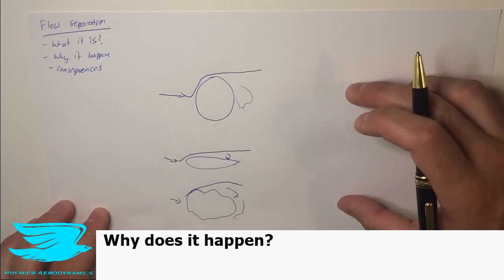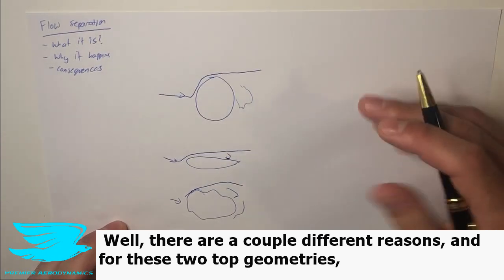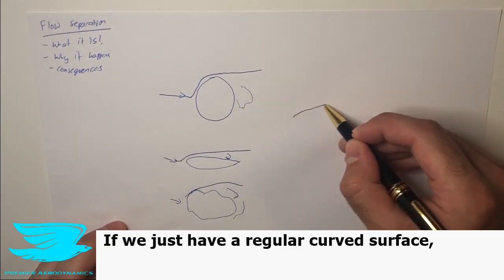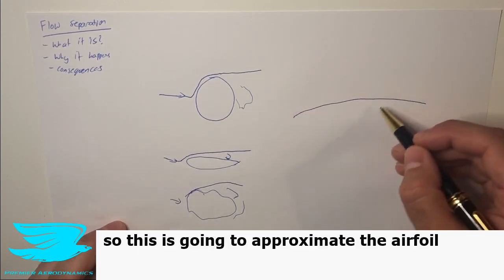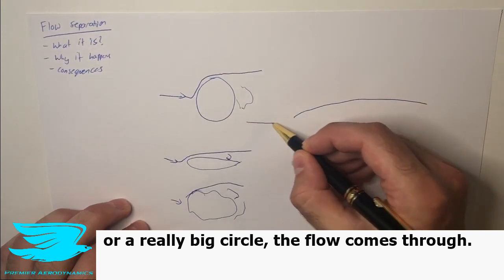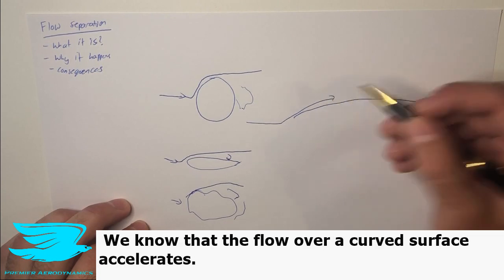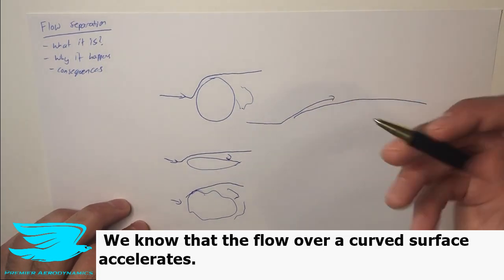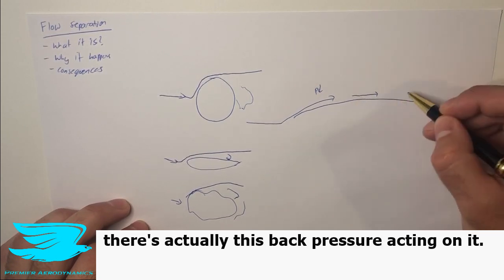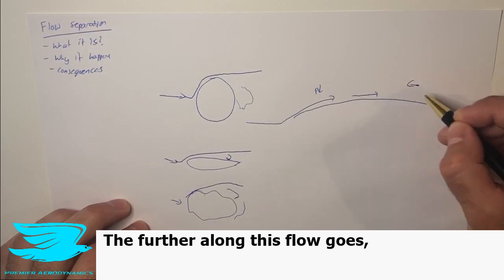So why does it happen? Well, there are a couple of different reasons. For these two top geometries, we're looking at something called the adverse pressure gradient. If we just have a regular curved surface, which can approximate the airfoil or a really big circle, the flow comes through, and as it goes over this surface, it starts to accelerate. We know that the flow over a curved surface starts to accelerate, so the pressure drops. But then once we get to a certain point, there's actually this back pressure acting on it. So the further along this flow goes, the higher the pressure gets.